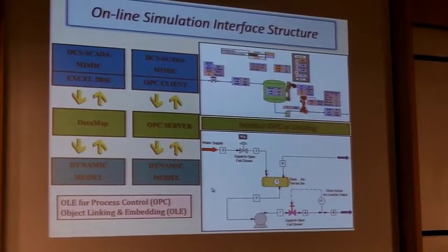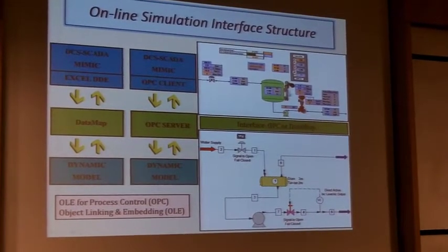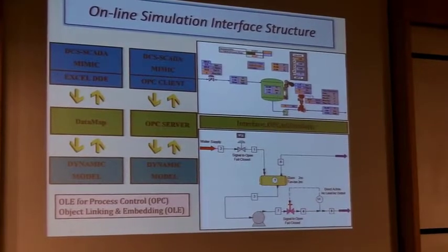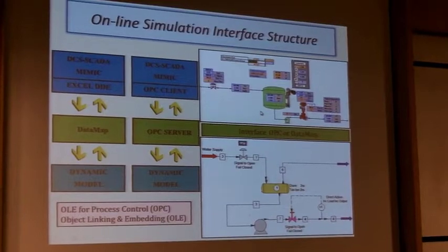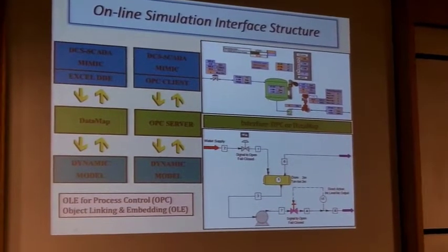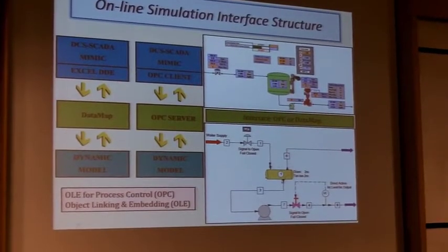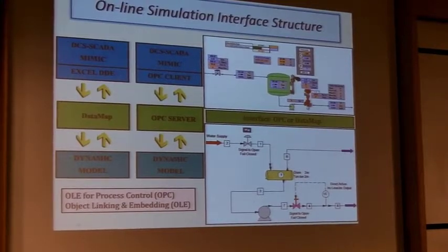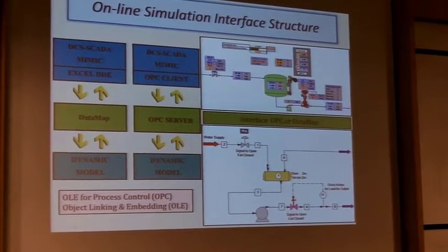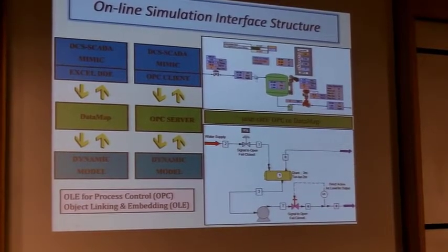So what you basically have, you have a simulation, which is this, and then you have a graphical interface control system. That's being built in Excel, that graphic. So it doesn't look like a typical DCS graphic, but it's the same principle. So that graphic's being built in DCL and links with this model here. So you can change tuning parameters in here. We can put different control valves in of different sizes and characteristics, and we can play with different feed rates and streams.